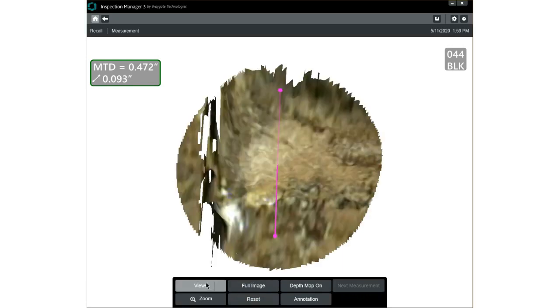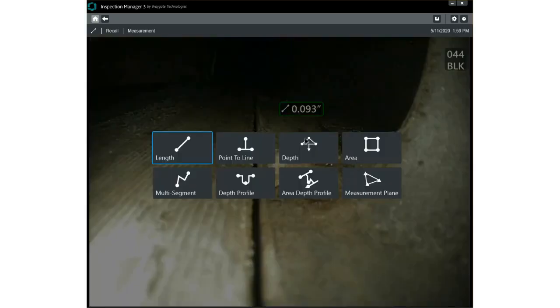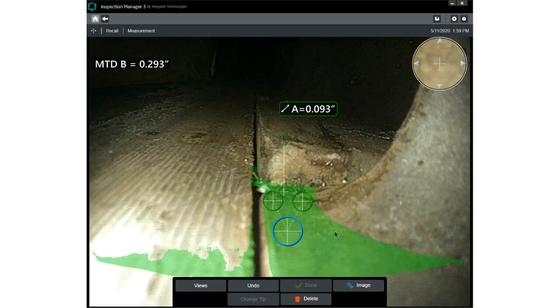So I'll reset the point cloud. In this case, I will go to the full image again, and I will add a measurement type where I can measure vertically and perpendicularly to this plane. So if I put 3 cursors in a depth measurement type on a surface, and those 3 cursors are congruent with that plane, you'll see a green surface mask, and that indicates all of the pixels currently masked in green are pixels that are very close to this mathematical plane of this depth measurement.